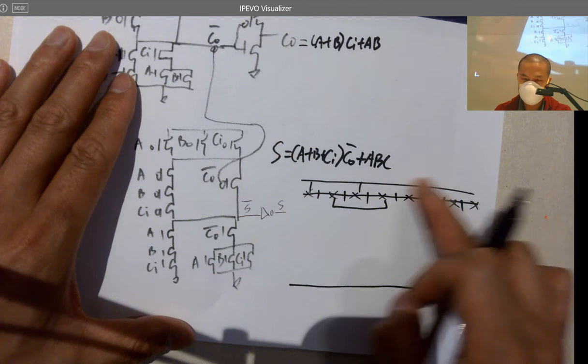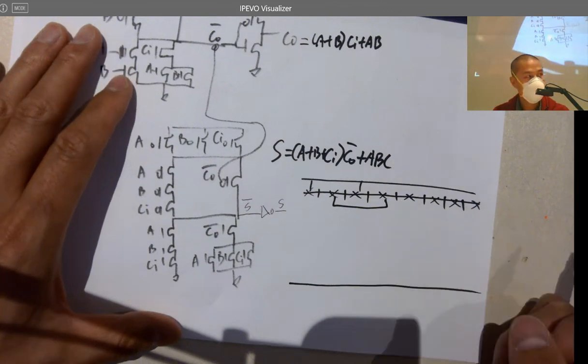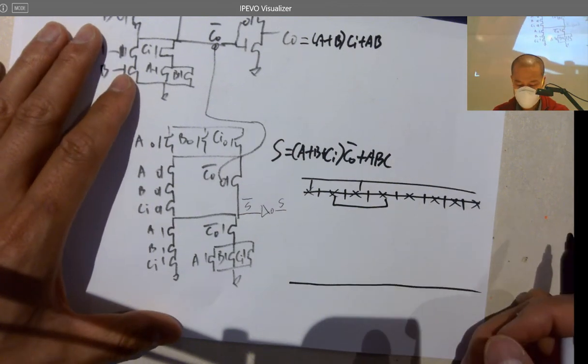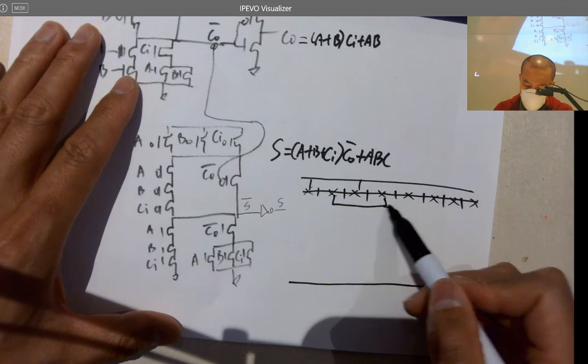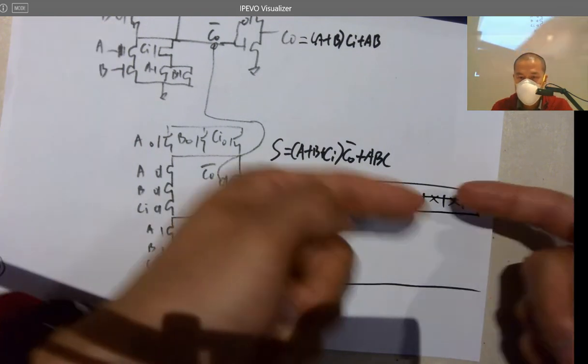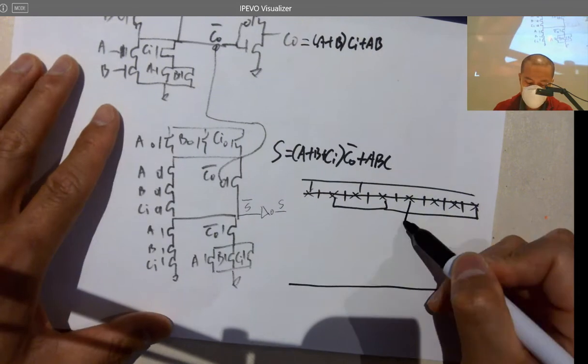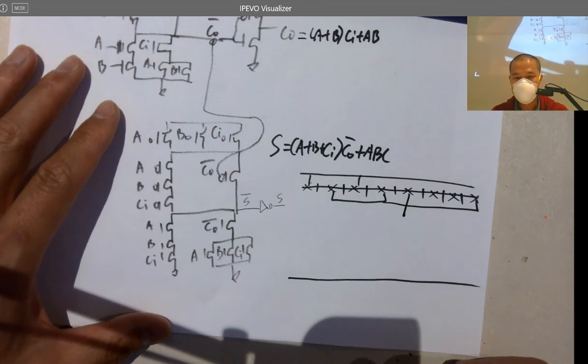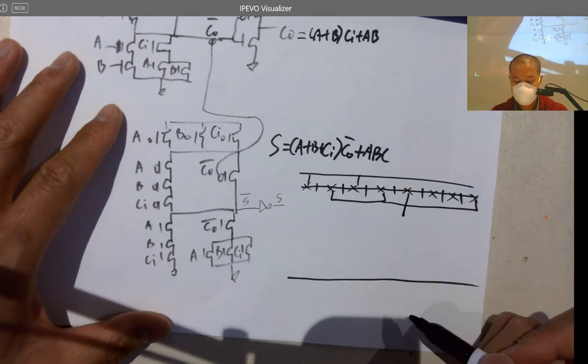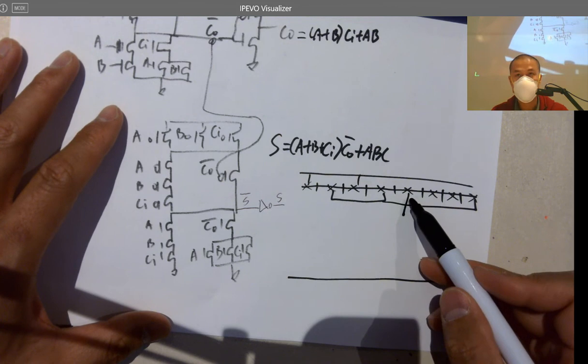So how do we do that from these 4 transistors? I just shorted to here to let the current merge in the middle. I'm getting a trace as an output from here. I have to deal with metal 2, I guess. I have to drill a hole to the top.